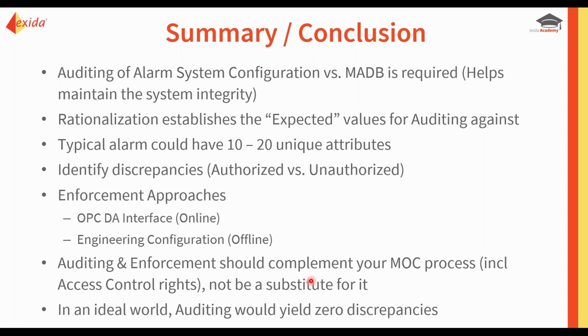So that goes into the MOC process, and ideally then you're using the MOC process of review and authorization before a change is made. Now, the change might be made in the control system first and then needs to be made in parallel with the master alarm database, or it could be made to the master alarm database first and pushed into the control system. Then you would know, if you did it that way, your systems would always be in sync and you'd never have any audit discrepancies, which in an ideal world should be the case.